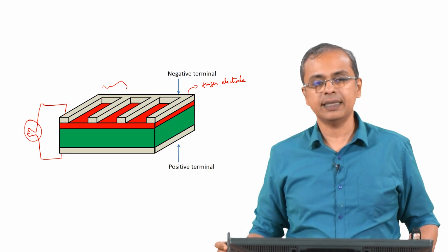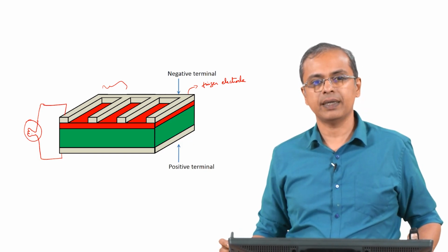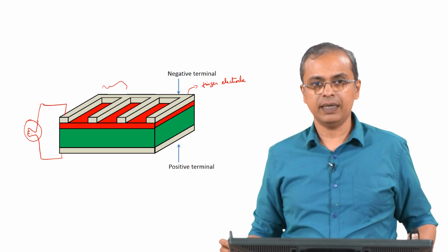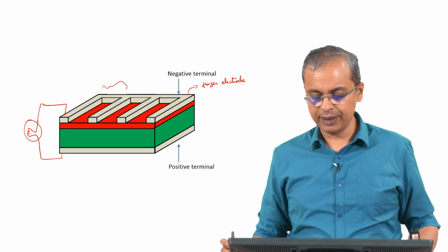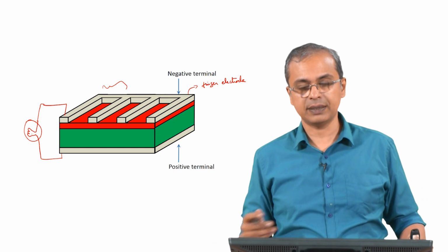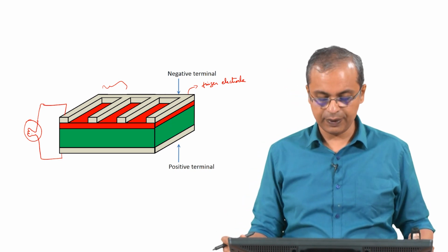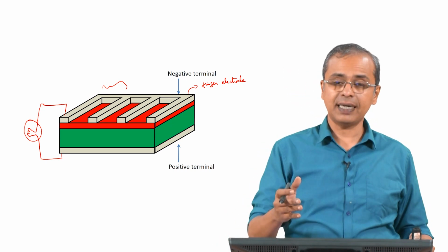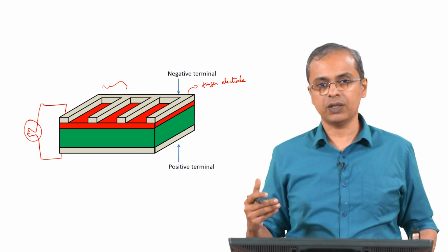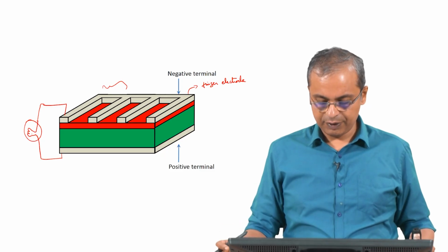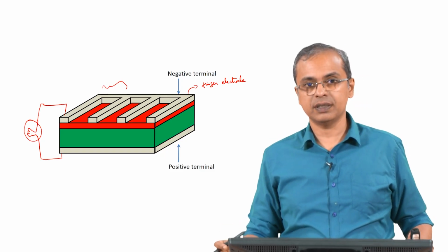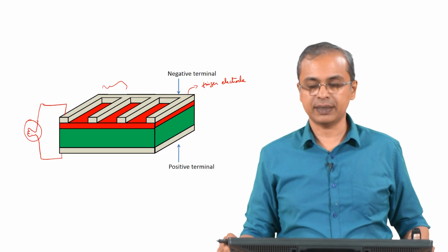So that is the structure that we basically create, which is the simple single PN junction based structure of a solar cell with a finger electrode on top and a continuous electrode at the bottom. So this is something we will keep in mind. We will make some variations and modifications on this, and we will try to understand what is possible.